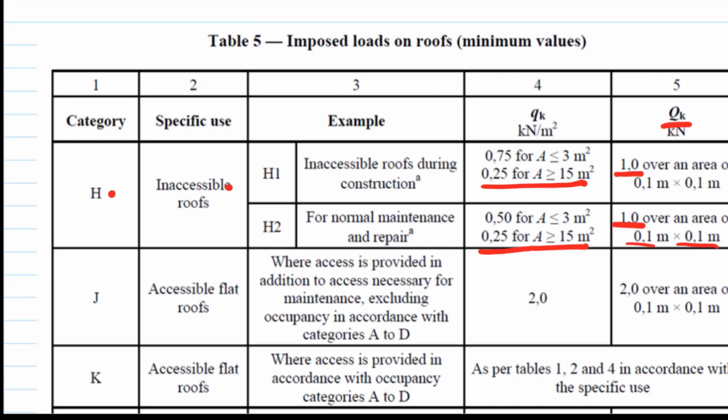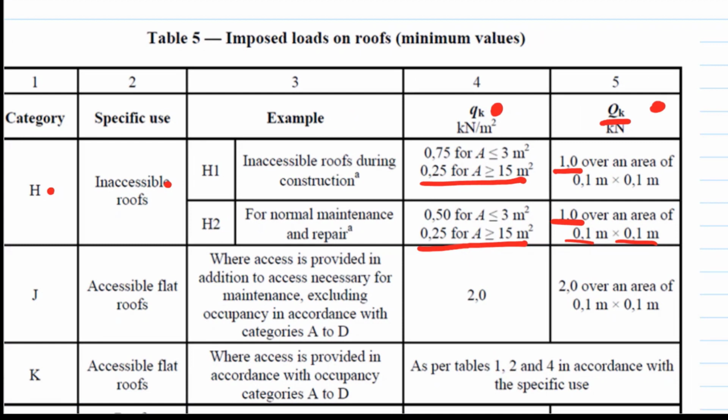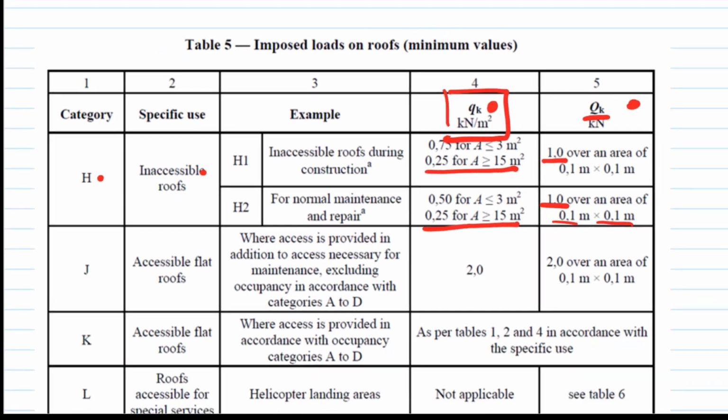You apply either one or the other, not both together. And since what we're doing is covering a large area, the distributed load will govern and not the point load. So we're only going to consider the distributed load in this case, but it wouldn't be wrong to take the point load as well.